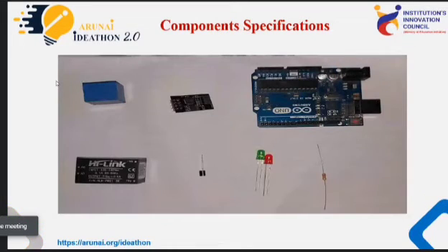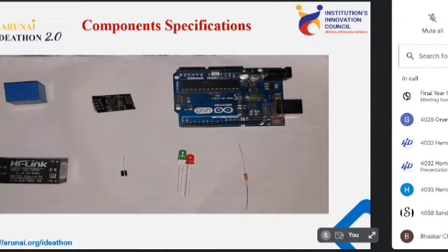Here the Arduino UNO is used to upload the programming code into the ESP01 node by using Arduino IDE. NodeMCU is the Wi-Fi module. We connect the Arduino and ESP01 to the breadboard through jumper wires. The AC to DC converter is used to convert the voltage.